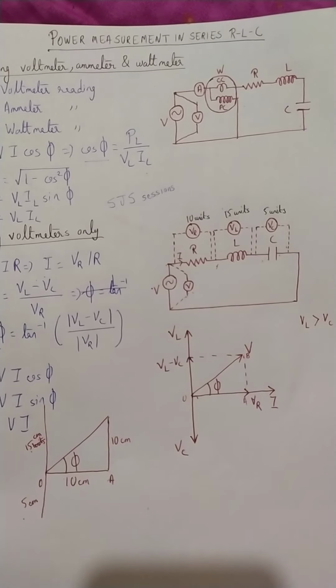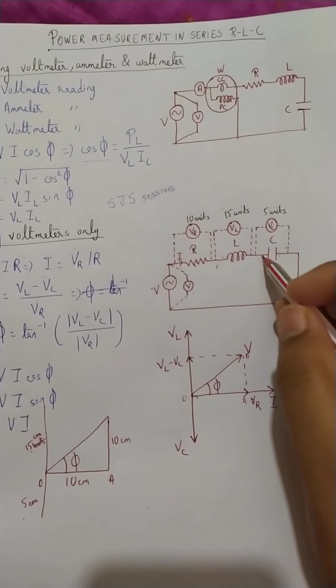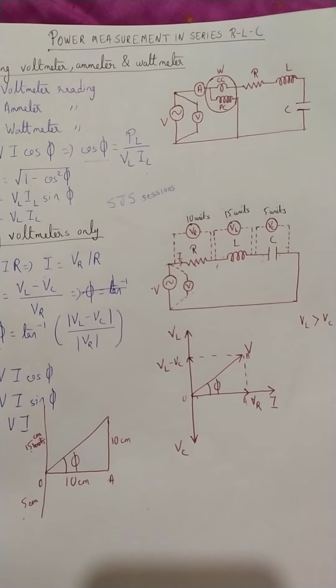This R might have some resistance as well as some inductance. This L might have some resistance, some inductance. This C might not be of perfect dielectric. It would have some imperfect material there, so it would be some RC sort of combination. Due to this there might be some difference in the results that we obtained by the two methods, but theoretically both of the methods are correct.